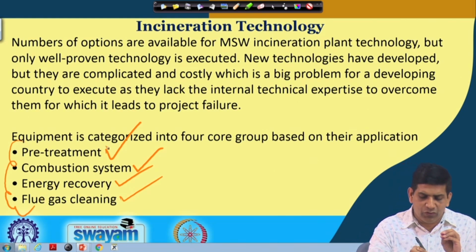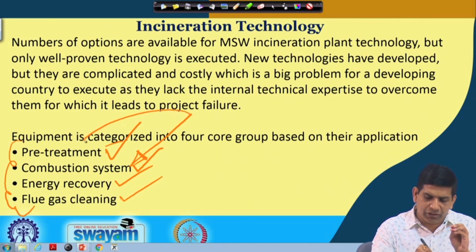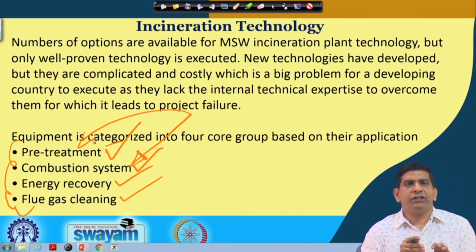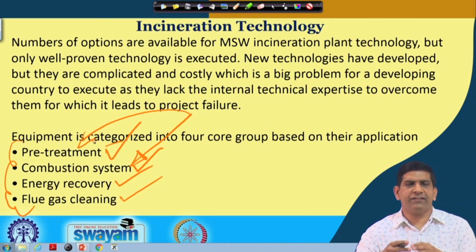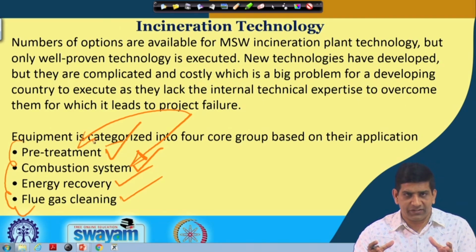So before waste goes to the combustion chamber, we have to make sure that there is nothing in there which will create problems, like small cylinders or some aerosol cans and those kinds of things which will cause a blast. So that needs to be taken care of.